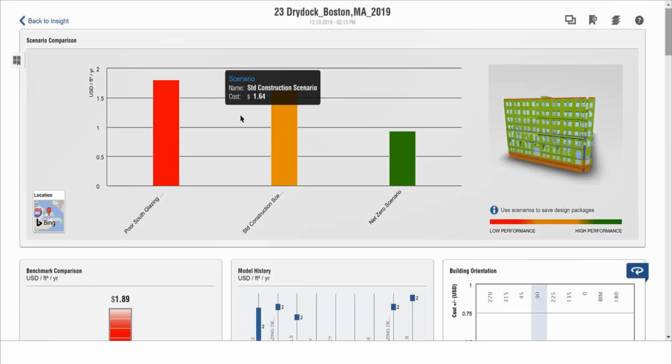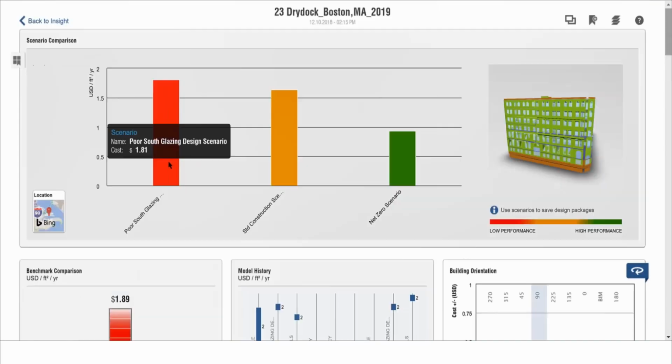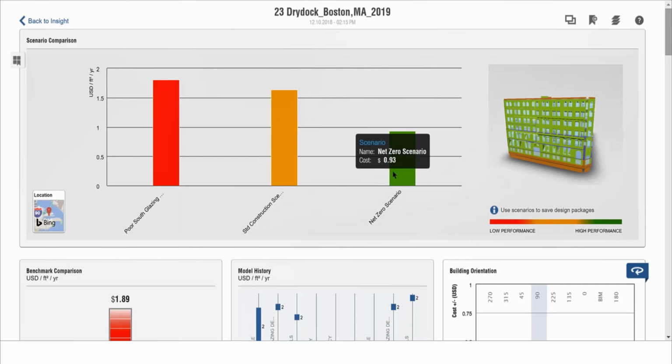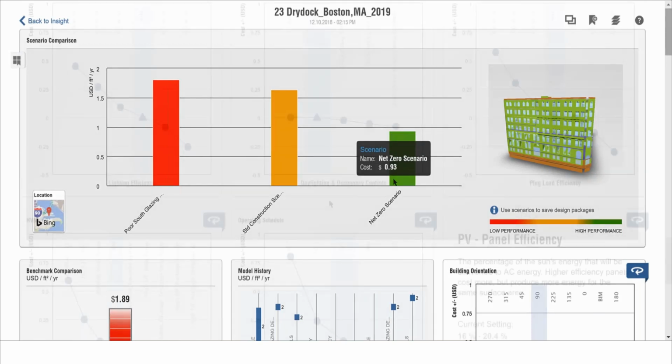And here you can see the scenarios, where red indicates the lower performance and green indicates the higher performance of the building, which is based on the ASHRAE standards. If it is below the specific ASHRAE standard, it goes to poor quality, and if it is perfectly achieving that ASHRAE standard, it comes in orange, and if it is a proper carbon neutral model, it comes in green.